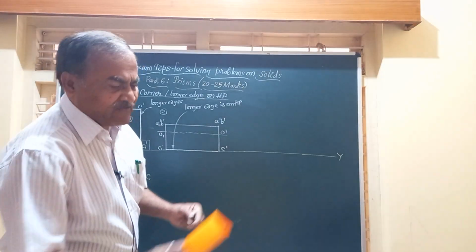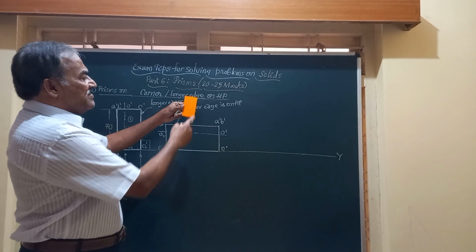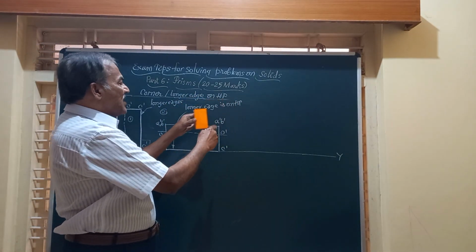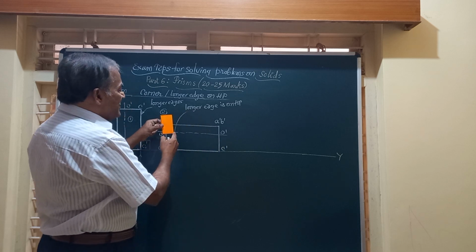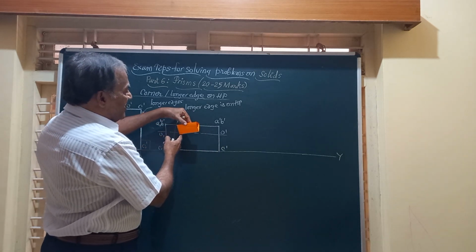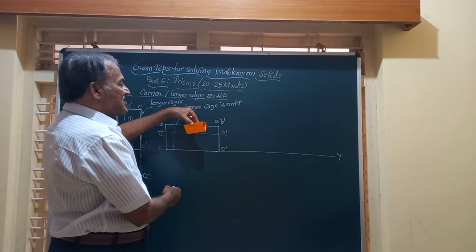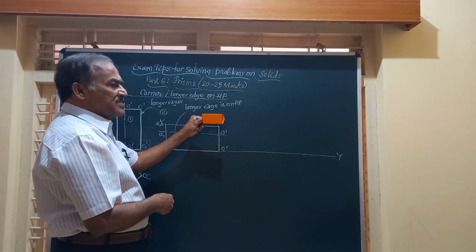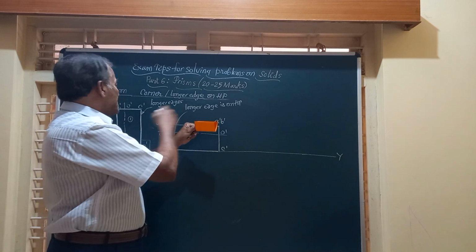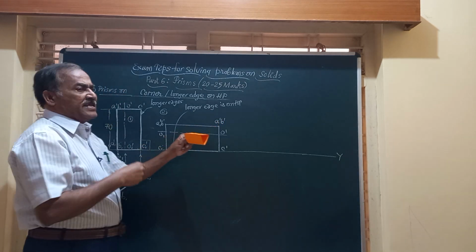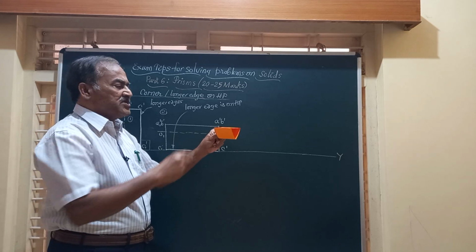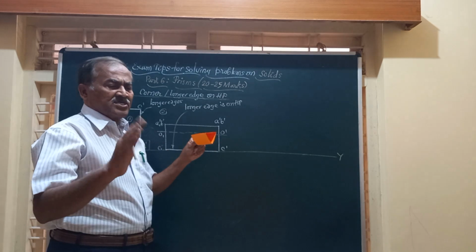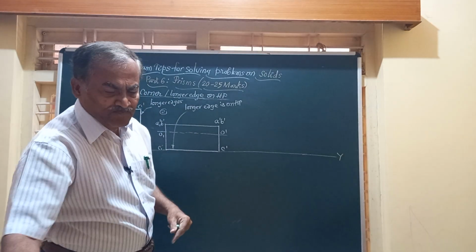Friends, this is very simple. Please, this was the figure. This is the longer edge, friends. And now I have to place the object on the longer edge, on HP. So I have rotated like that. Friends, let us see how it looks in the top view. Friends, in the top view, one of these rectangular faces A dash B dash A1 dash B1 dash is visible, and only the edge on which it is resting is not visible in the top view.